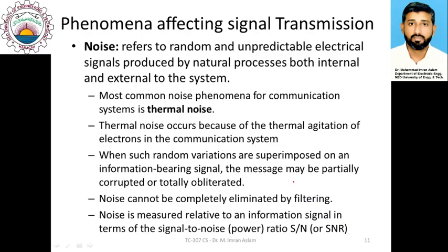But if we have a signal of, for example, 1 watt and noise of 0.0001 watt, in that case the effect of noise would be negligible, because the noise is significantly smaller as compared to the signal. So treating noise independently does not make any sense. We have to consider noise in comparison to the signal strength.